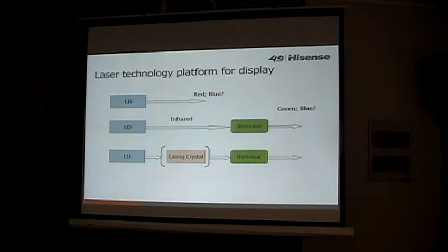We can just apply voltage because they are simply pin junctions. We can get a very efficient conversion from electricity to laser optical power. And another important point from the material point of view is that semiconductor material for lasers is made by similar or the same technology and equipment as integrated electronics, so it can achieve economies of scale, and we all know integrated electronics can be made very small.